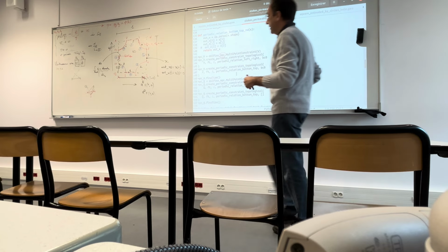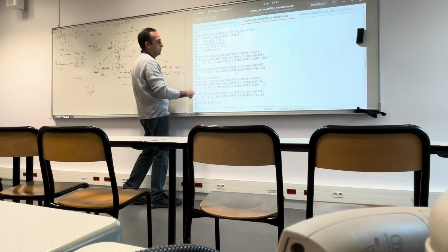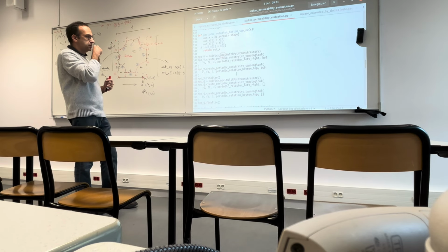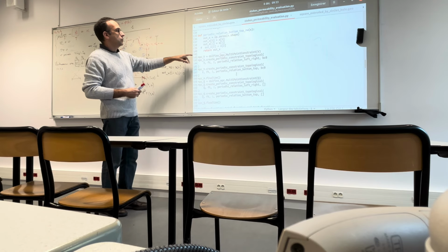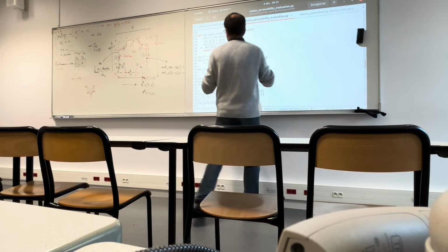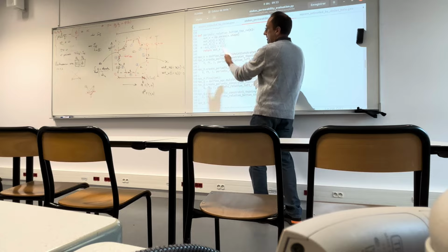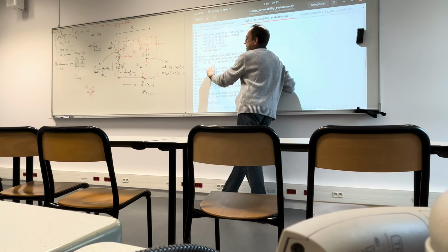So I'm defining this MPCV and this MPCQ to specify periodic boundary conditions on velocity and pressure. And so you see that what I'm doing is to create a topological periodic constraint on the base of what? On the base of this periodic relation left-right that we have defined before, applied to what? To points belonging to the part of the boundary having a label 2.